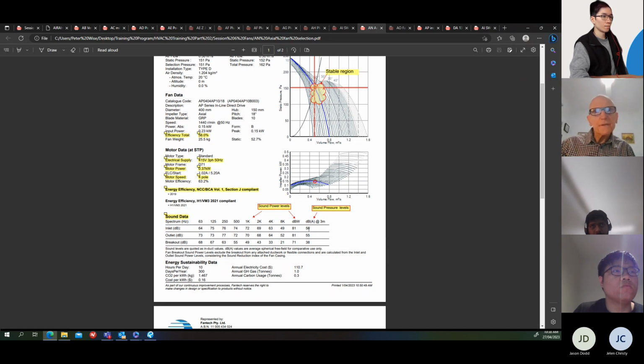That's a discussion for another time. It's quite detailed discussion, but to do a proper acoustic analysis, you need to start with the sound power levels and work through. Now, Fantech do have an acoustic analysis program. I don't know whether you've used it, but if you work through that, put in the fan data, all the duct work, it'll go right through those calculations, and if you need an attenuator, it'll tell you what attenuator you need. So that's quite helpful.